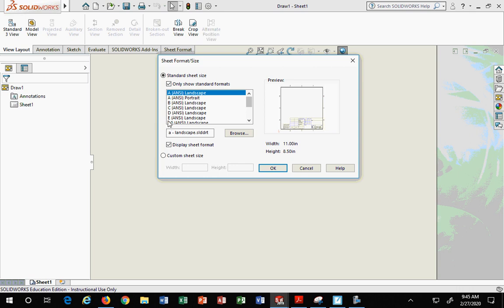So you have to follow the standards of the printer that you are working with and the paper sizes you are working with, regardless of what units of measurement you are using on the drawing. Please make a note of that. Many times a person will use the paper standard based on the units of measurement they're using on the drawing, and then the outcome is they can't print it because their printer is set to a different paper size.